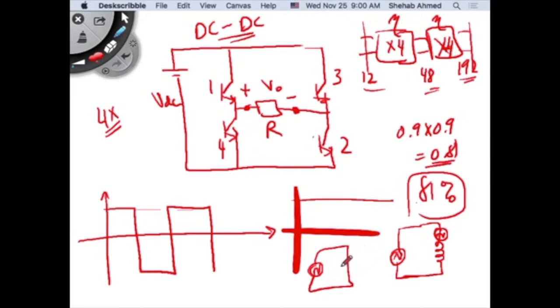So the resistance of the wire will limit the current. That's it. So you're going to be pushing a huge amount of current through. Pushing a huge amount of current through, you saturate the transformer. It's useless. You're not building a transformer anymore. You're building a heater, right? So only when the winding is able to generate the back EMF, and when is it able to do that? When you push an AC waveform through it.